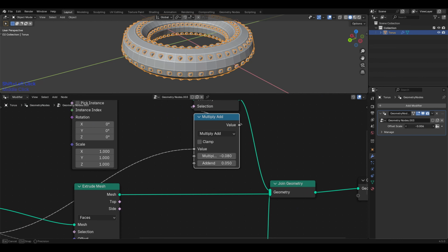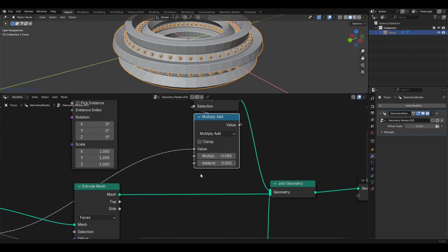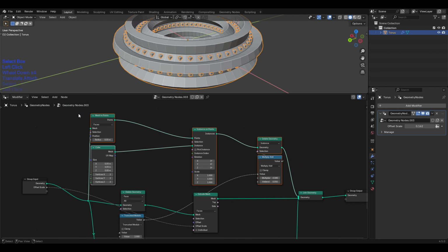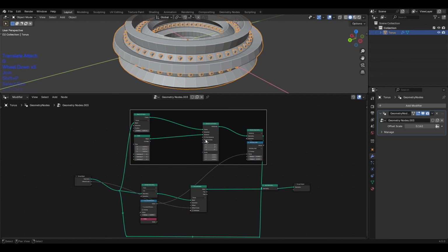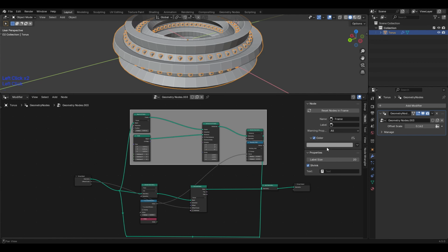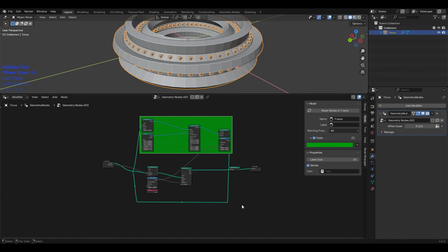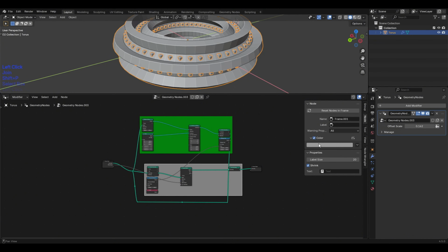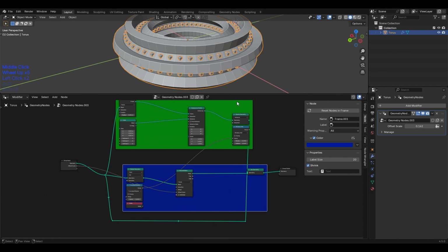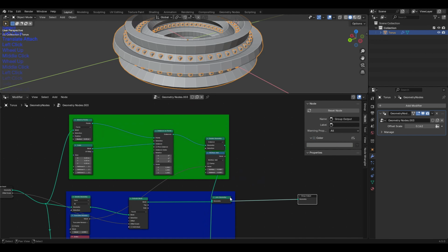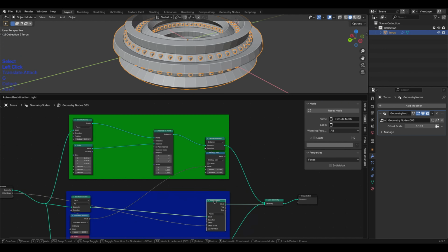As I do my extrusion, you can see those instances are gone from there. We can do a small amount of cleanup here. Shift P for Blender 4.5 and up will bring the framing in, and I can go to node, add color, something like that. Then we can add another one here. Shift P works good, and now we get something a little bit cleaner. I always like a little bit of housekeeping, it keeps things logical, which is nice. And I think Alt P will pop that out of there, and then we can straighten things up.